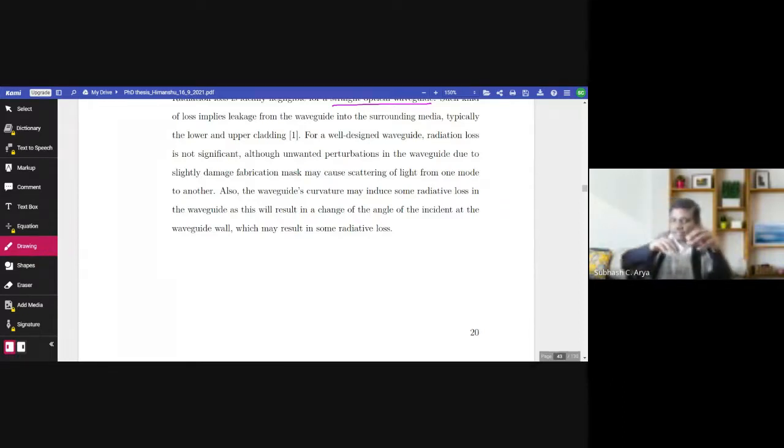However, if the waveguide is bending, what happens at the bending? There is a deformation in the dimension of the waveguide. That will break the condition of light propagation, say total internal reflection. Then because of that, there will be radiation of the light because of, say, the evanescent field, etc. So that radiation of light will lead to the loss of light.